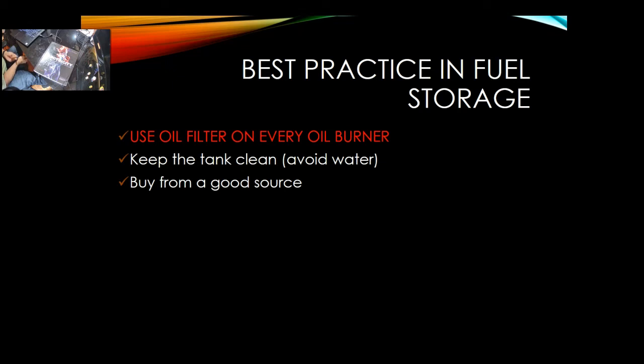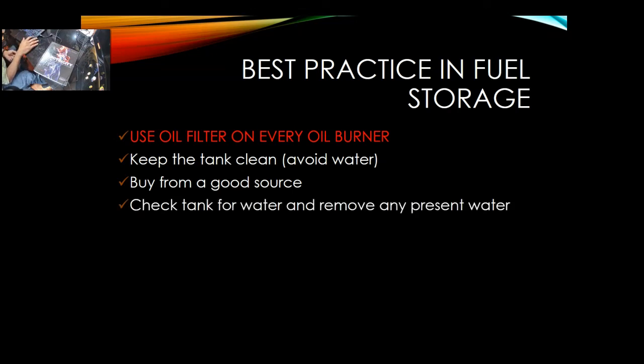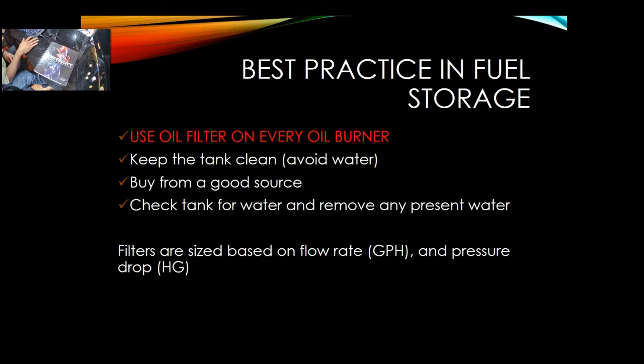When you bring in air, air has some water coming with it. So eventually you'll have a lot of condensation, and this is how you have water. And also buy from a good source. Check the tank for water, remove any present water. Filters are sized based on the flow rate and pressure drop. So again, that's something you have to look at when you change those filters.